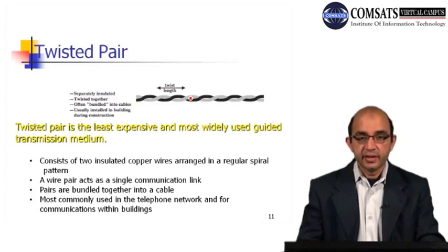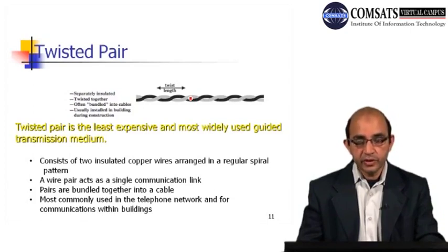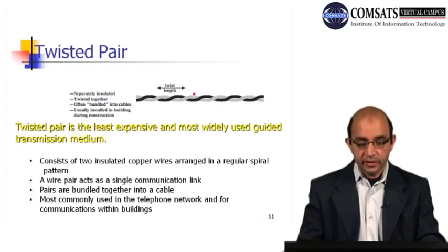As a result, the data can be distorted, or there can be some noise, or we can have errors regarding the data communication. So we have twisted the pair in such a way that EMI from one cable is cancelled by the EMI from the other cable, right? So this is the reason for giving twist to this pair, right?